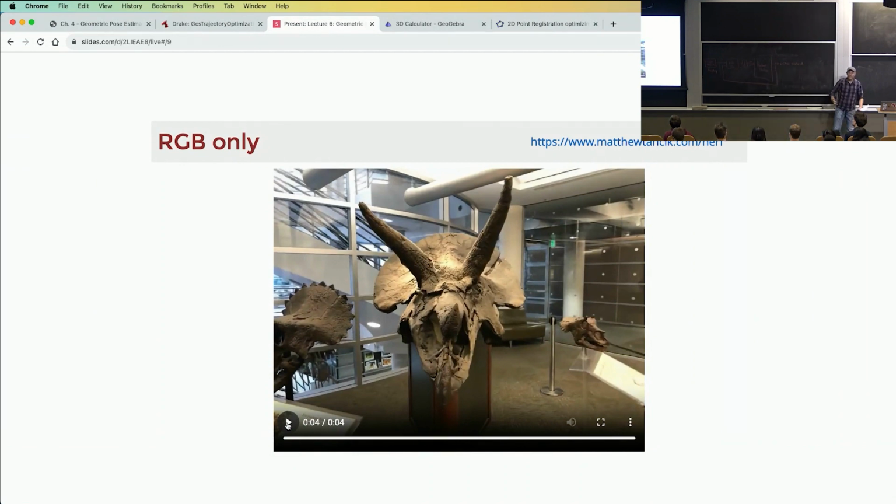There are also lines of work in monocular depth with a very clever approach: drive a car around with two cameras on it, use the second camera for stereo matching, but learn a model from the single camera to the depth. Then, when it's time to make 100 million of them because you're going to make it into a product, you just take away that extra camera and use the learned mapping from image to depth. So monocular depth is a surprisingly effective technology now.